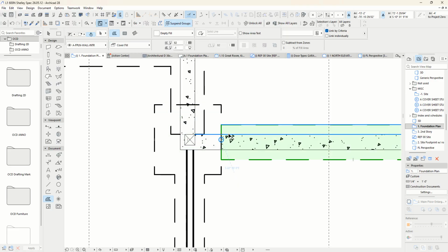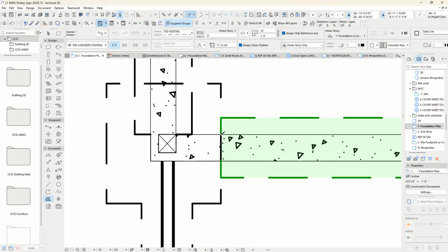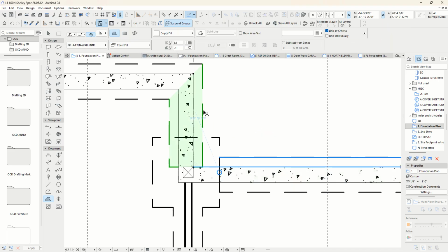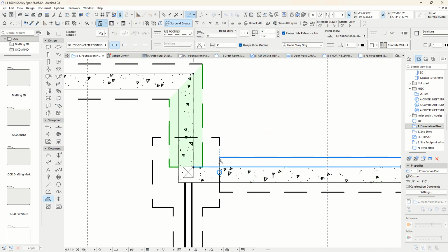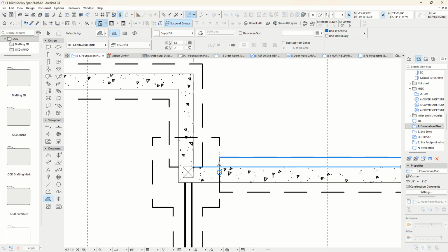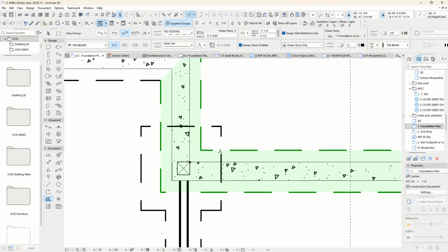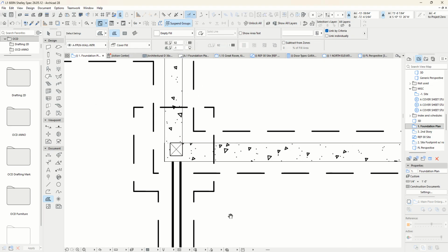And if I look at this one, the reference line is set so that it centers this wall on this beam, and the beam reference line is the outside of the wall, which works really good. Pretty typical for how I'm doing this. You can see there's your reference line, and so I can take those and merge, and they just line up under the beam great.